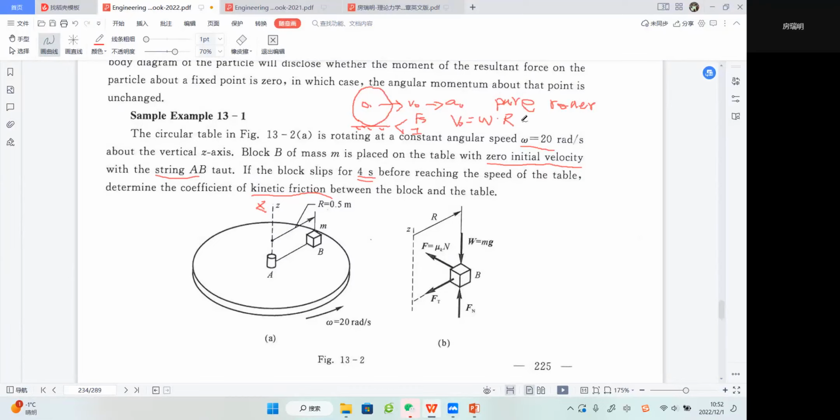And then we take the derivative of both sides of this expression. The derivative of v0 will be a0, its acceleration along the horizontal line, right? And this one will be alpha, meaning angular acceleration, times r. So this is a very important thing that we have learned. I do a quick review, and I hope you guys can understand it a little bit more.